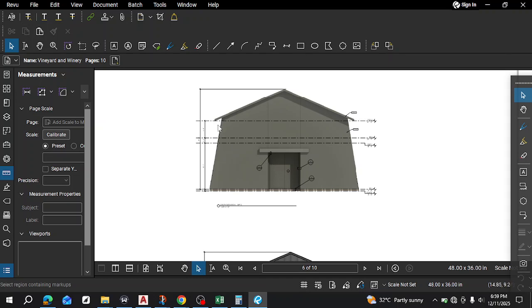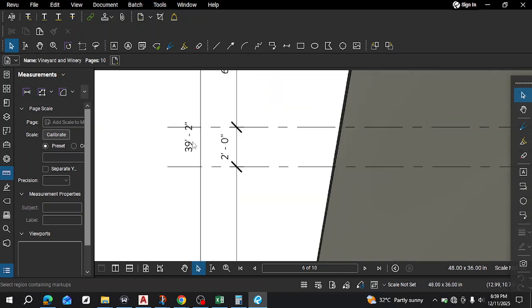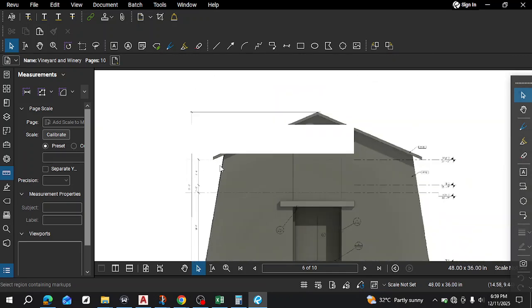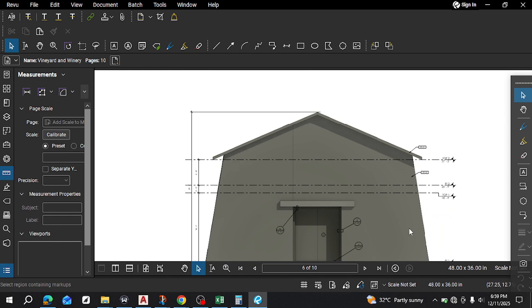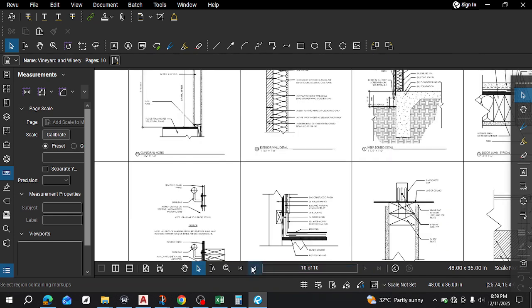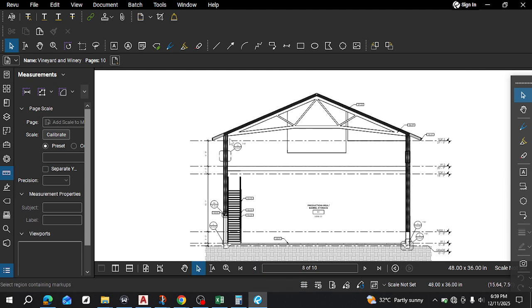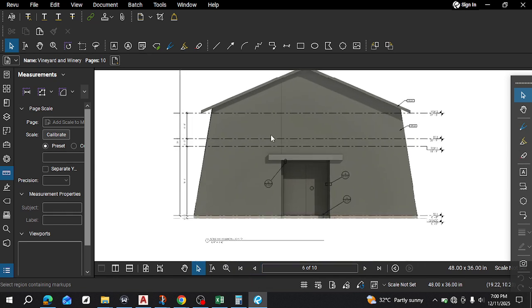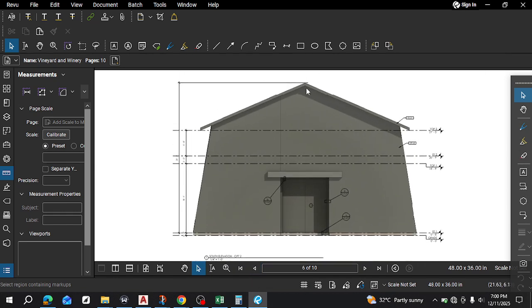So now we are going to do some estimation, right? I used 39 feet as the height of this building. If it had a ceiling here, I would have taken that as the height of the building, because ceilings are what separate it from the roof. But being that everything is open to the top, I'm taking it that the whole building is conditioned as one large space. That's why I took 39 as the entire height of this building.